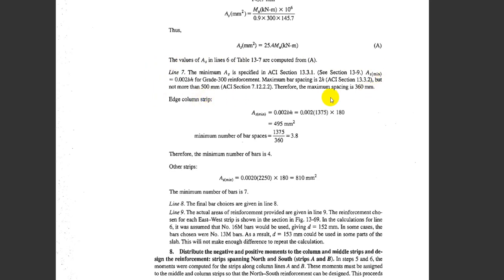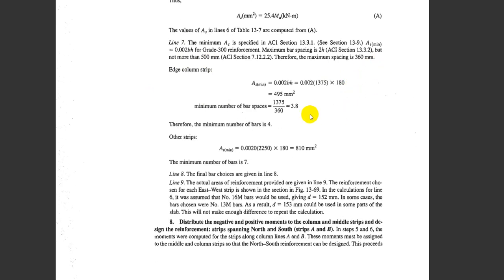And people will recognize you with your good details. Alright? So that your minimum rebar, if you are assuming that your maximum spacing, if you're using maximum spacing 116 millimeter, and this is the width of the slab, you need at least 4 in order to meet the maximum rebar spacing on the slabs like this. Okay, so let's take a look if you have a minimum rebars more than 4 or not.